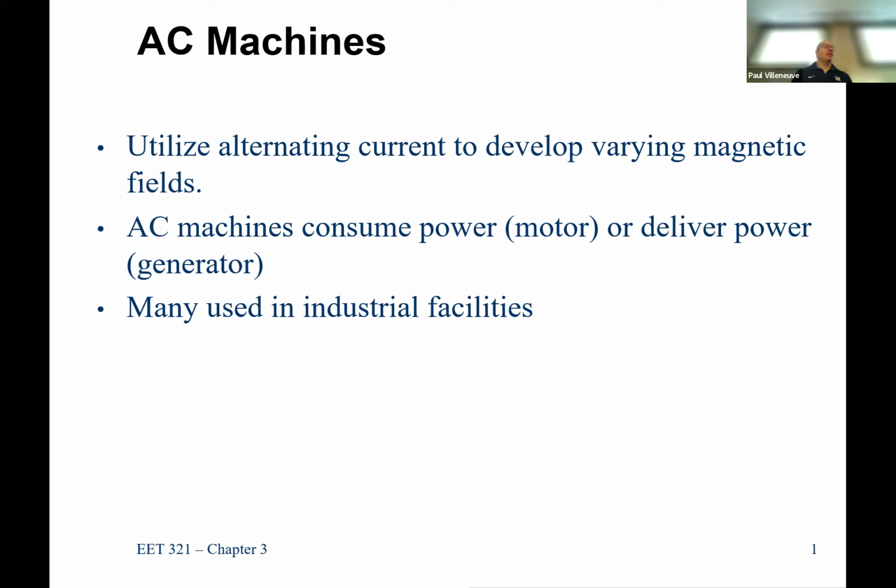So you might find some DC machines in cordless power equipment or even corded power equipment because you're trying to maintain a lot of speed control, and AC machines don't do that very well. That's the issue, if you will, with AC machines. If you have to do speed control, you really have to do a lot of work, whereas with a DC machine it's quite a bit easier. In fact, there is an alternating value inside the DC machine. It just doesn't appear from that perspective.